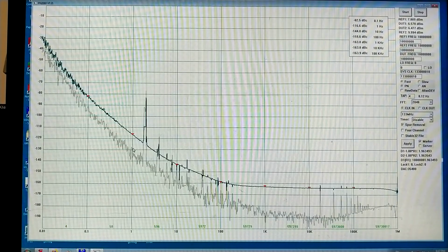And then I would want the amplifier noise to be 6 decibels below that. That would be minus 135. And this means that I need nearly 20 decibels lower noise from the amplifier.